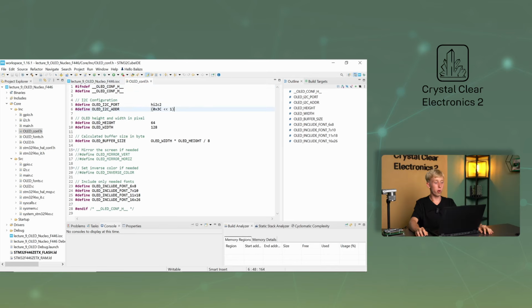The pointer given to the port points to the generated I2C structure, which is in the main.c file. The address is 3C hex as found in the datasheet, which must be shifted by 1 bit during transmission. I understand that our goal as software developers is transparent and reusable coding, which facilitates easy interchangeability and integration of software modules or software components. But why does this make our code modular?